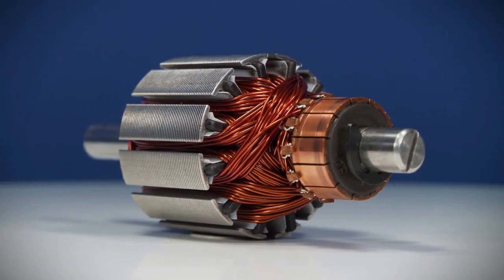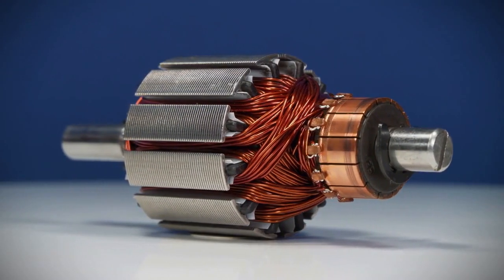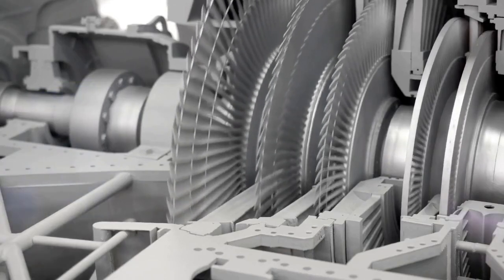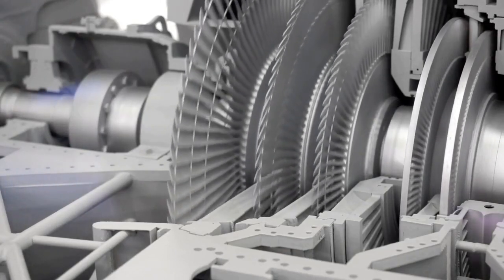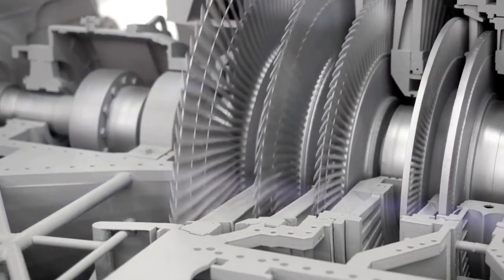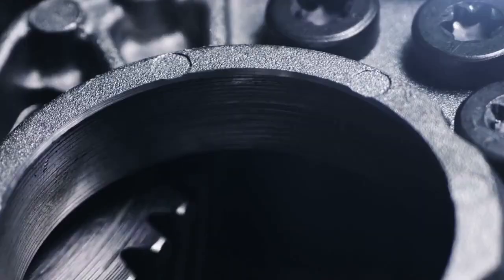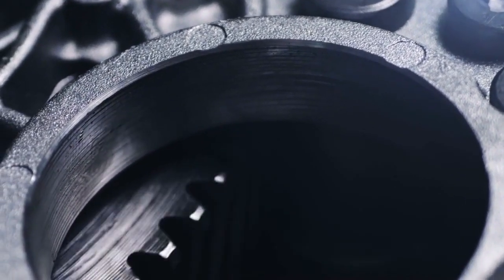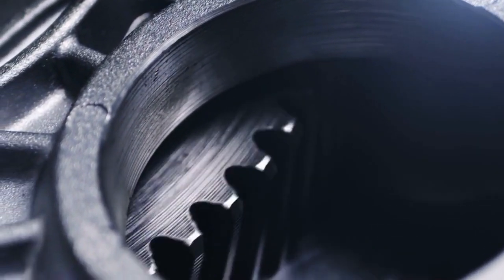So, what is it? First, let's quickly remember what work is in thermodynamics. Work is a way of transferring energy when a force causes movement. A classic example is a gas in a cylinder pushing a piston. That's called boundary work because the system's boundary itself moves.